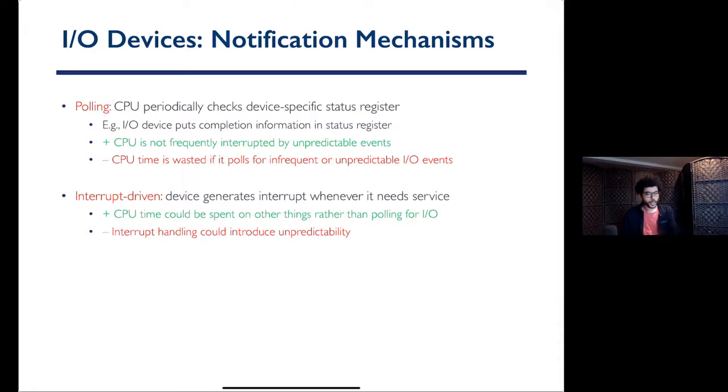communication with the device. So in this one, the plus side is that you're not wasting CPU cycles on waiting. But the downside, we have seen it in real-time systems, is that it provides unpredictability, right? You're running your application and then an interrupt happens and the application gets interrupted. Now you don't know how long it takes for the interrupt to be handled.